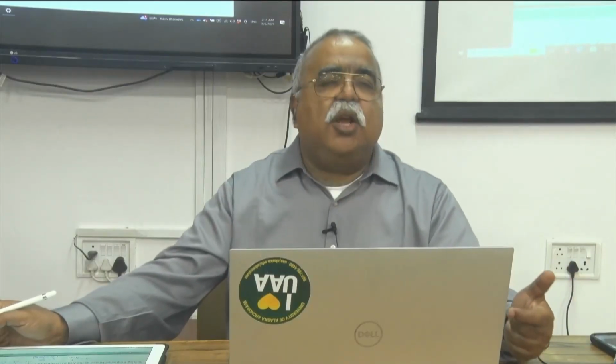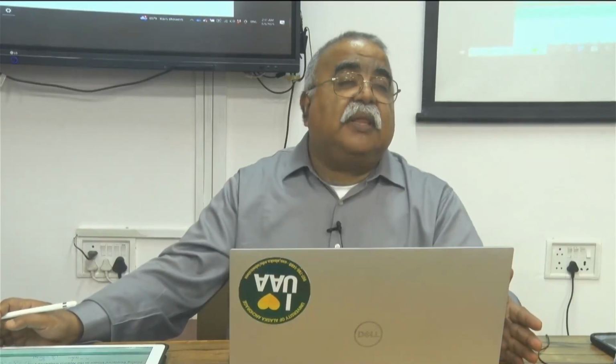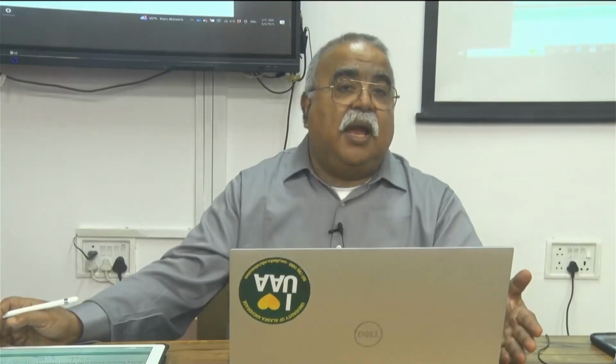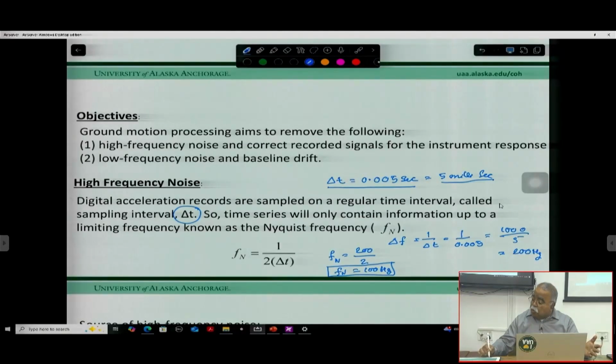So the maximum frequency you can use is the Nyquist frequency, which is 1 over 2 delta t, right? If you want to explore the frequency content of 150 hertz, then you have to have a sampling frequency greater than 150. So 1 over 2 delta t has to equal, say, 150 hertz. Calculate what your delta t should be: 1/300.